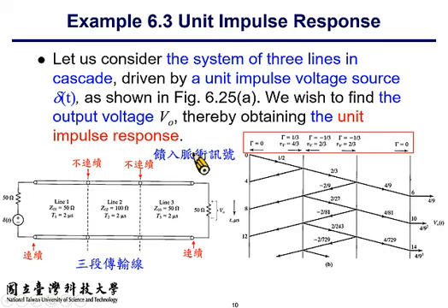Alright, so to the left hand side we have the delta signal, an impulse source, and the internal resistance of the source is 50 ohm, which is the same as the characteristic impedance of line 1. So it's a matching case. And to the right is the termination, which is a 50 ohm termination. Again, it's the same as the characteristic impedance of line 3.